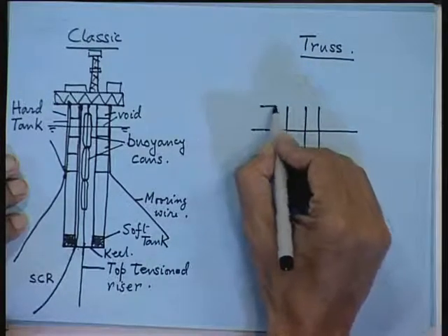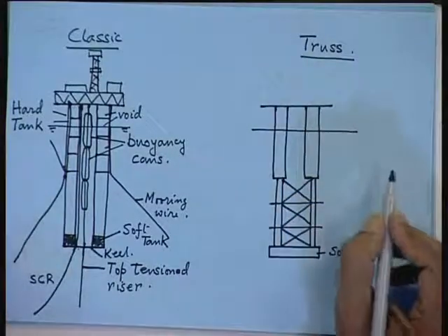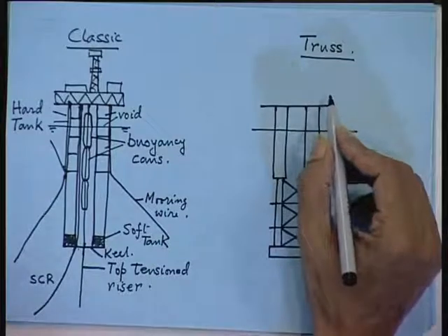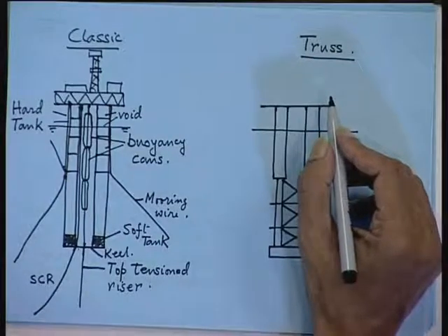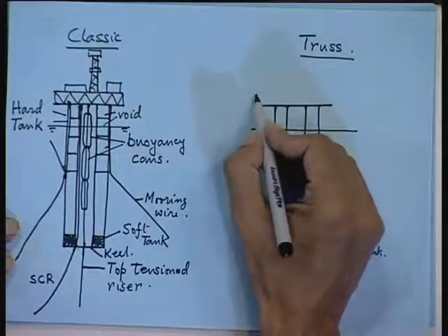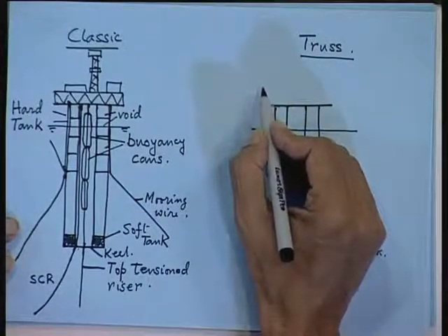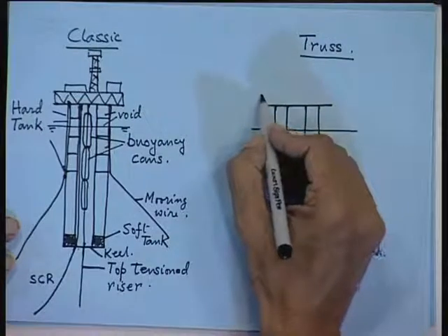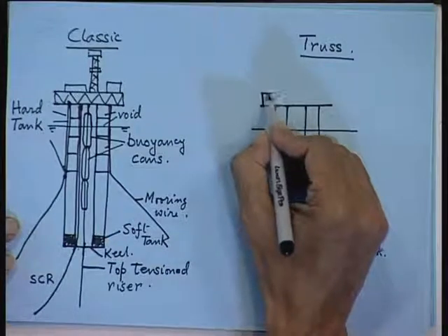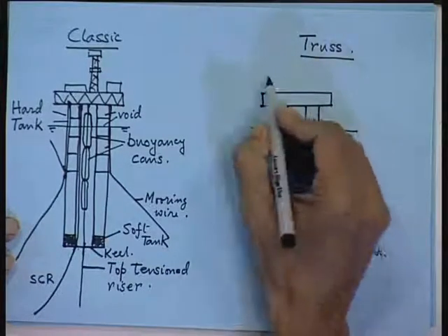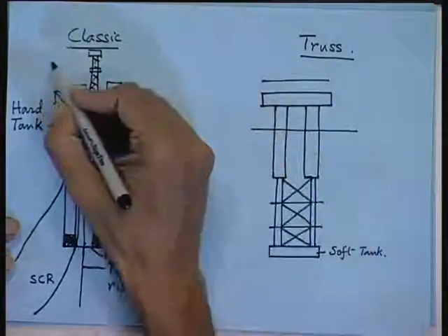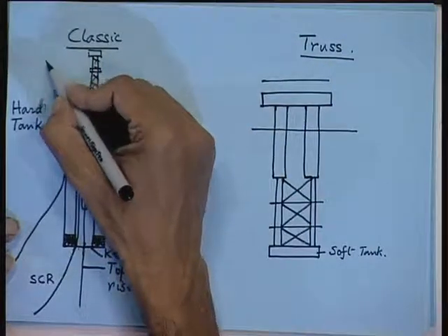now all these offshore structures, basic thing you should remember that the riser has to be kept under tension. So, that acts as a weight. So, you have to increase your displacement, or you have to provide sufficient buoyancy for riser support and mooring supports. So, this is somewhat your departure from the conventional ship design that we talk about. So, here you can have a flare stack,